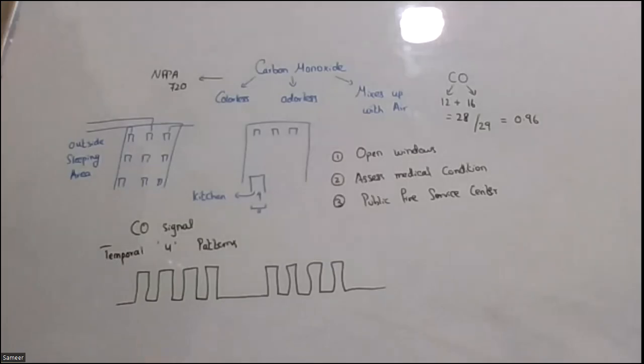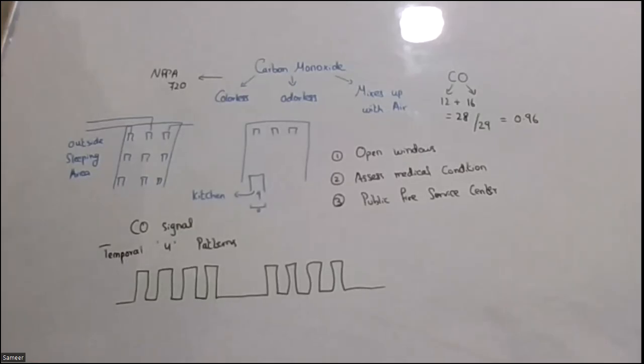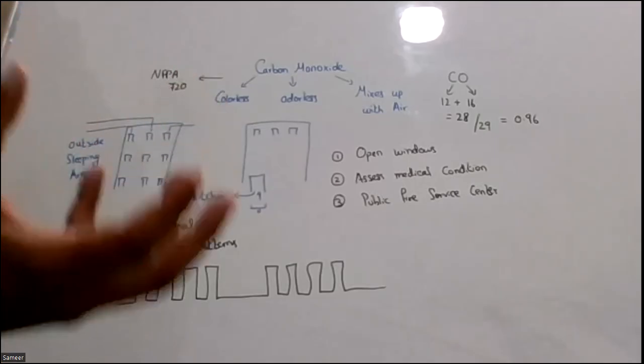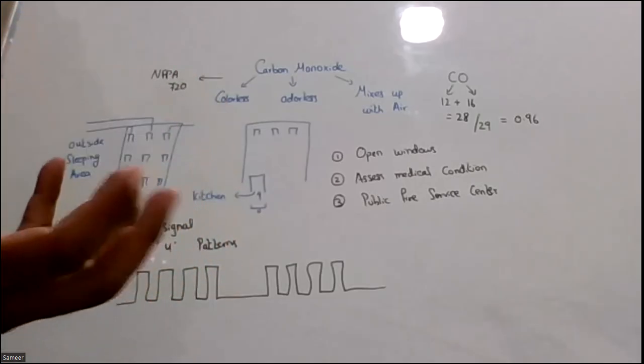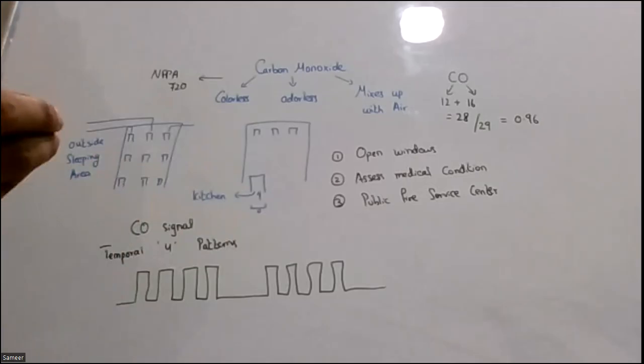Now the second important point of inspection, testing, and maintenance is that once your devices are faulty, you should get a fault signal directly at your control panel. So your initiating devices should be well tested, and the sensitivity should not be reduced.